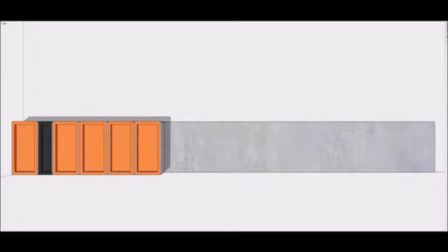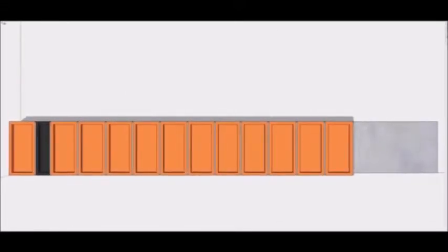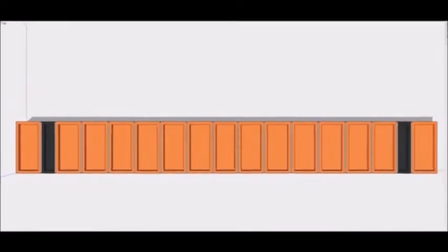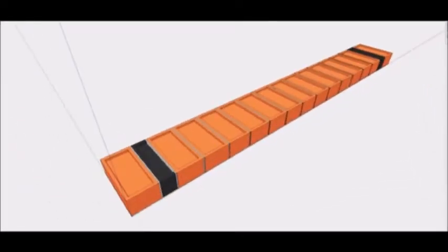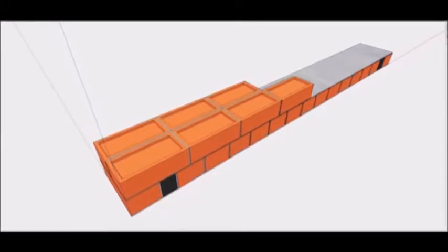The general arrangement of bricks in this type of bonding is similar to that of English bond, except that the heading courses are only inserted at every 4th or 6th course. Usually the arrangement consists of 1 course of headers to 3 courses of stretchers. A queen closer is placed next to the quoin header of the heading course to give the necessary lap.